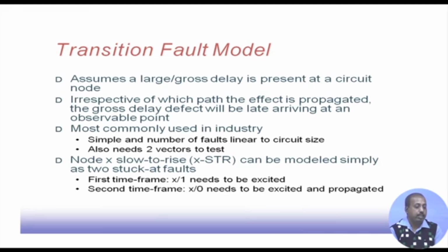So, in the first time frame we apply the pattern corresponding to x stuck-at 1, and the necessity is that it must excite the fault. We do not need to propagate the fault to the output at this point of time. However, in the second time frame I want x stuck-at 0.